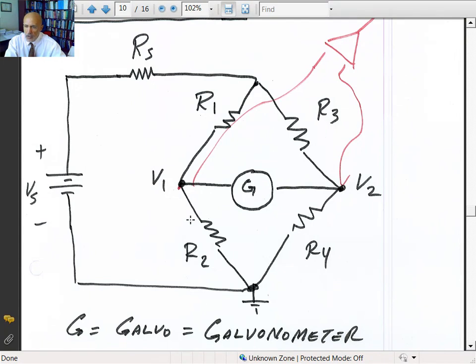What you can do is put some kind of photoresistor in one of the resistances here, let's say R2. Like in a revolving door or automatic door in the supermarket, as soon as you get closer to the door, because the light intensity is changing on the photoresistor, its resistance will change and the bridge will no longer be balanced.